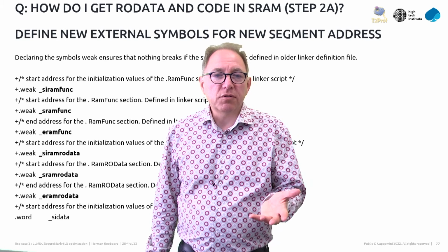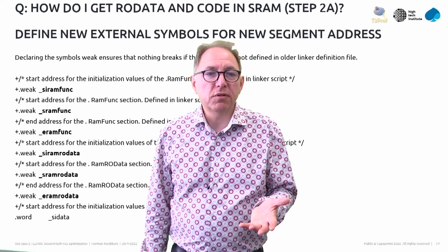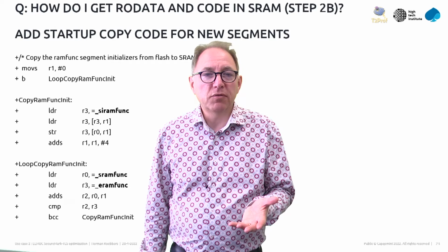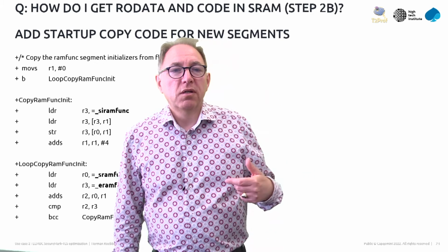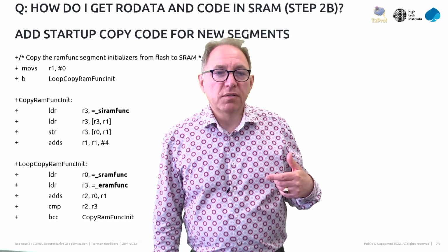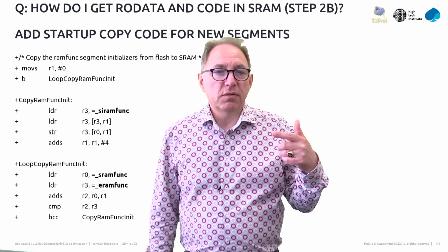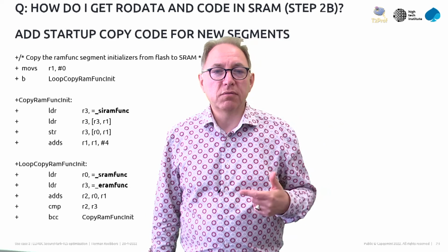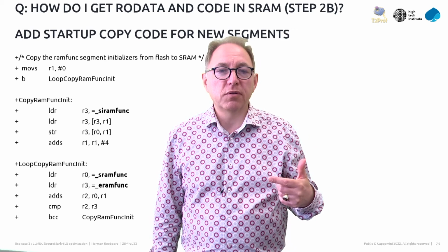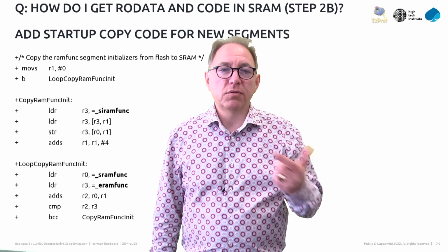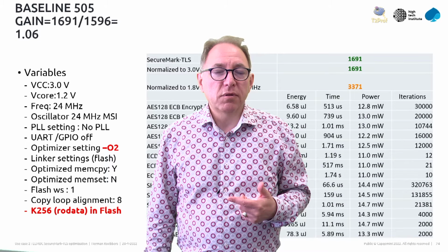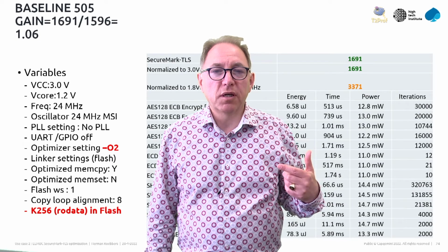We define these extra symbols so that we can actually get a successful link. And here's a bit of code that actually copies the code and the data, so from the flash to the RAM. So this is the part where we copy the code to this RAM, and we have a similar part for the read-only data.